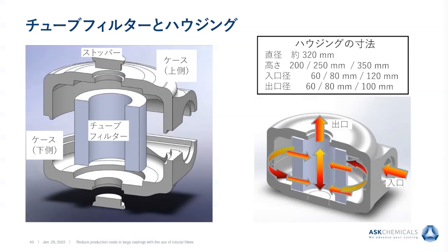The use and the installation of the tubular filters within the mold are different, but no more difficult than the use of any standard plate filters. In fact, the installation of this filter is simplified because tubular filters are designed for easy installation within the mold near the mold cavity. You can also place them directly near the ingate, or you can use a suitable filter print.